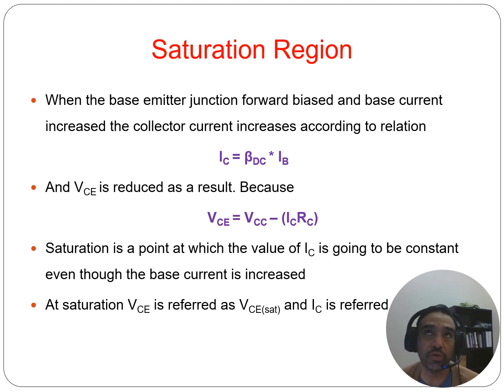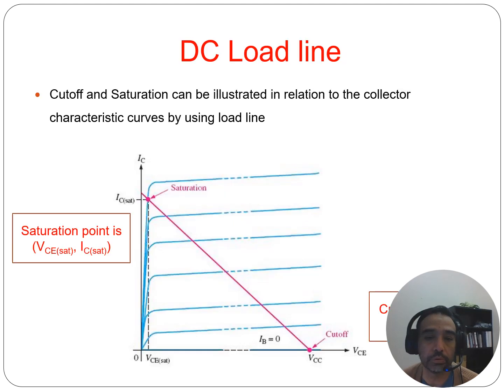So when we say VCE, voltage collector-emitter at saturation, that means the collector-emitter voltage when the transistor is fully on, right? What is that voltage? And when we say I sub C under saturation, that's the maximum collector current when the transistor is in the saturation region. And you can get those from the graphs. So you get the graph that can tell you what to expect from the transistor. All right, let's keep going.